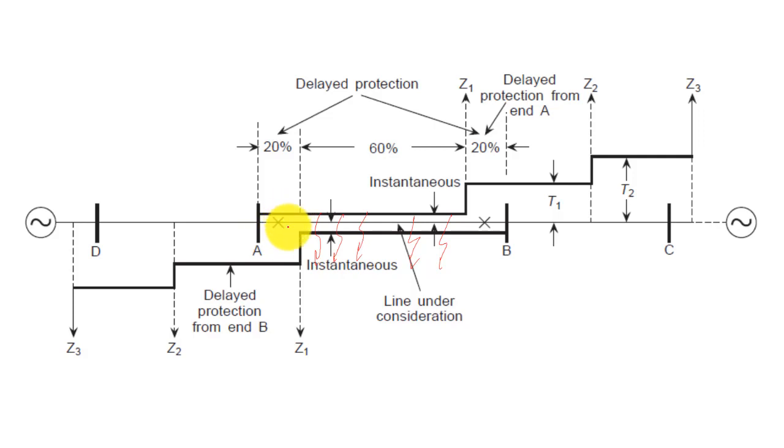But when the fault is here somewhere or here somewhere, right, then obviously at the local ends on both sides, one breaker will trip instantaneously but the other breaker will have delayed operation. So the line is not tripped instantaneously, which is the requirement for the reclosure scheme, because most of the faults in practice are transient, around 80% of the faults.